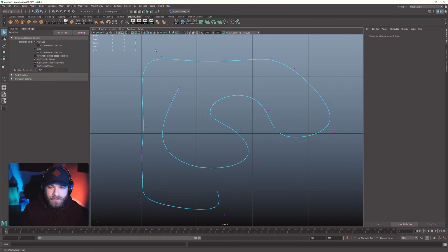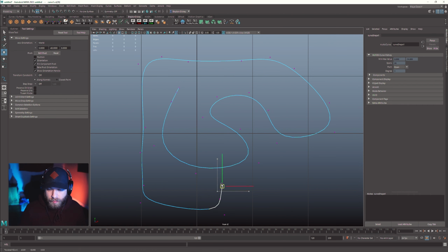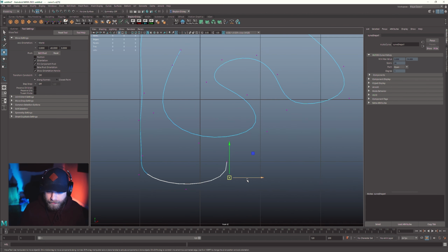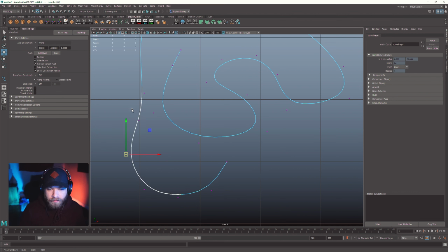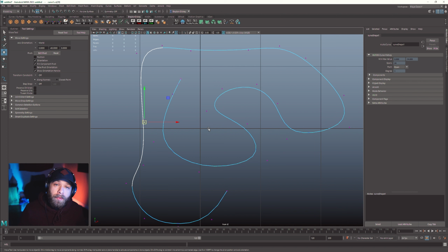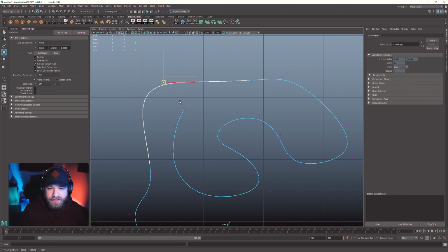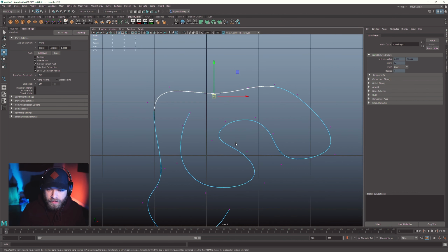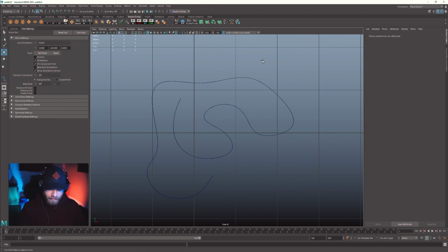If I hit enter, for example, to accept that curve, and then right click and go to control vertex, you can see this is your initial point here, and everything else is like these influence curves that you can use to drag out the curves. So that's how you can modify the curve after the fact, which is part of the power of using the sweep mesh tool to make your wiring and cables: being able to edit the curve after the fact pretty efficiently and conveniently.